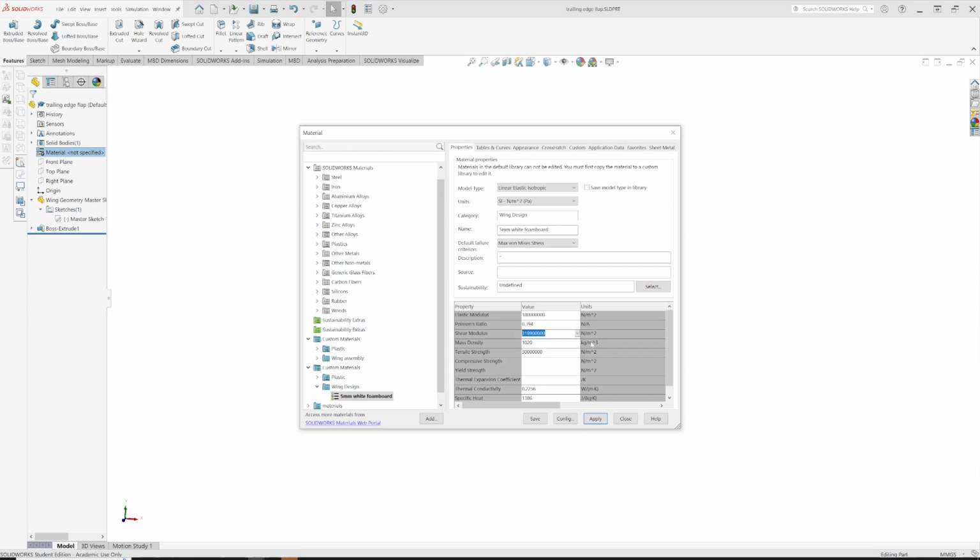So shear modulus. Elastic modulus is the stiffness in pulling, shear modulus is the stiffness in shearing, so we'll need that because our beam will be shearing as well. So looking up on the spreadsheet again, I can see our shear modulus G is 2.1 times 10 to the 7.